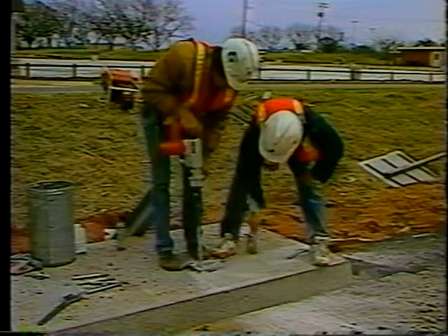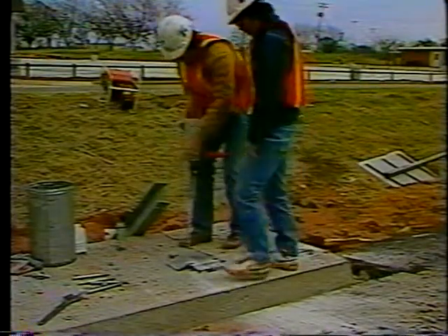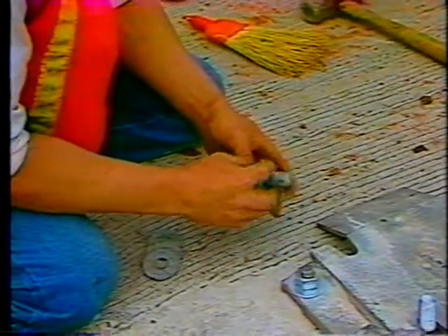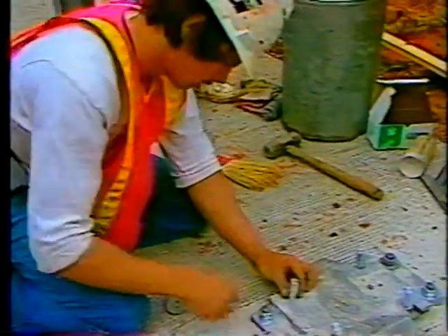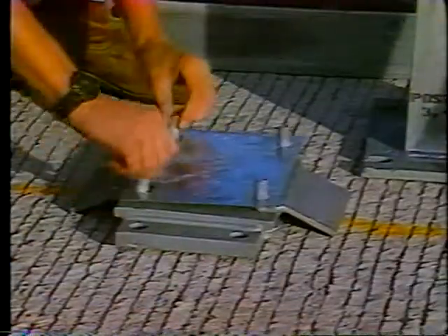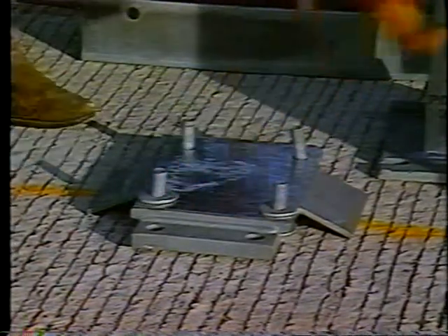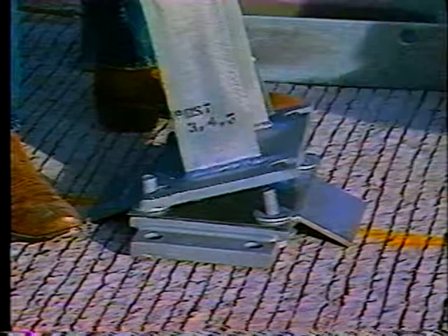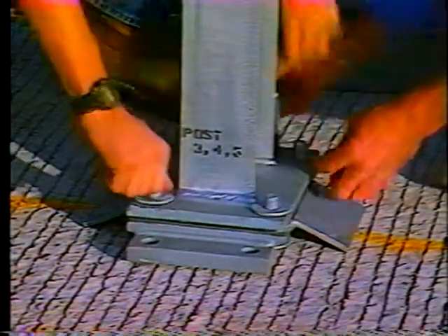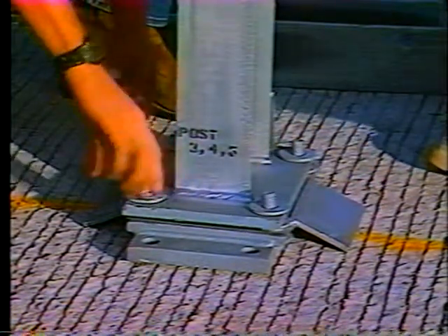Assemble post 1 in place first. Mount the base to the concrete by drilling the hole and then tightening down the bolts. Next, place 4 hex head bolts head down in the base slots with a flat washer on each bolt. Then place the keeper plate onto each slip base, followed by 1 flat washer on each base plate bolt. Position the post base over the bolts, followed by a flat washer and nut. Torque the nuts to 75 foot-pounds plus or minus 5 foot-pounds.